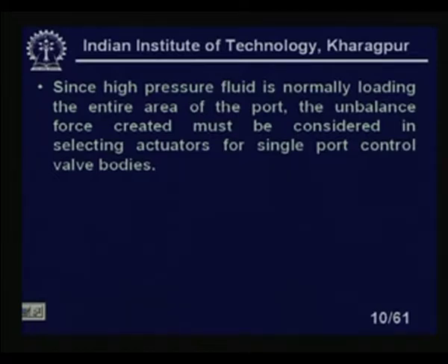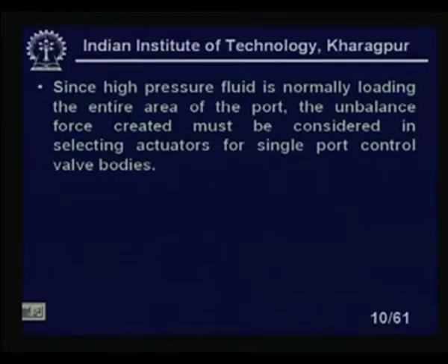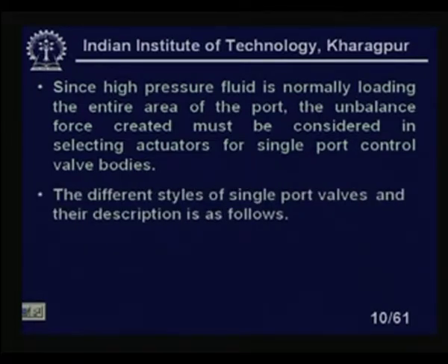If the liquid is coming at high pressure, quite obviously it will occupy the entire area of the inlet port of the valve, and the unbalanced force created must be considered in selecting the actuators for single port control valve bodies. The different styles of single port valves and their descriptions are as follows.